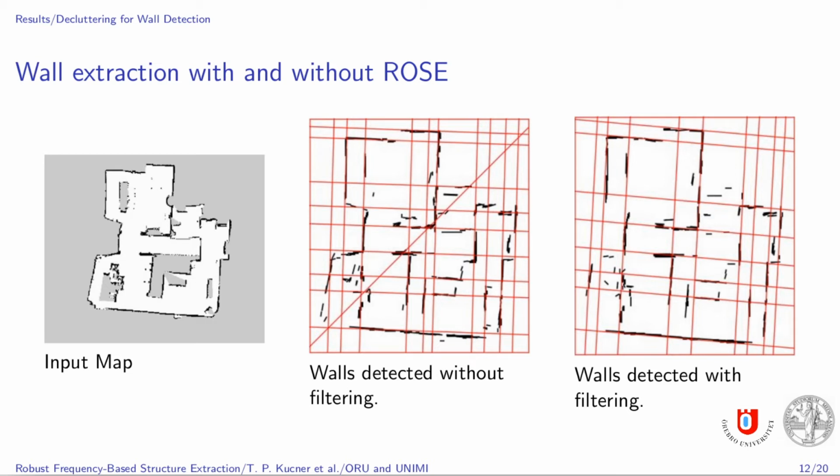The process of room segmentation is a way to automatically split the map into semantically meaningful regions, rooms. However, the process is sensitive to clutter and misaligned walls. Both can be falsely identified as walls and lead to oversegmentation of the environment. Thus, the filtering step, removing the clutter and misalignments, allows to mitigate their impact.